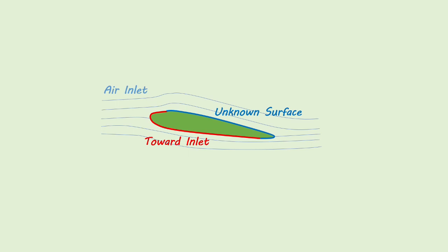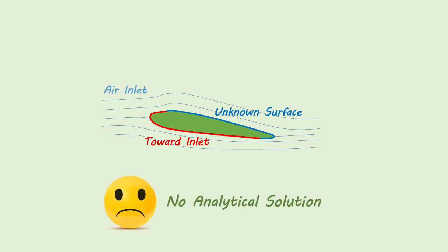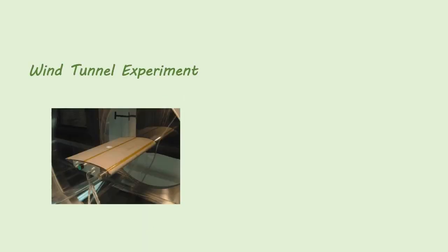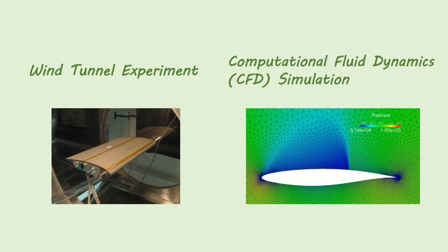What is the biggest challenge in obtaining these parameters? The answer is that this is a complex fluid dynamics problem that cannot derive analytical solutions. As the surface that does not face the inlet has an unknown pressure distribution, it can only be obtained through experimental measurement or CFD simulations. So the developability of the airfoil is very weak, as any optimization process must exist in CFD series software.